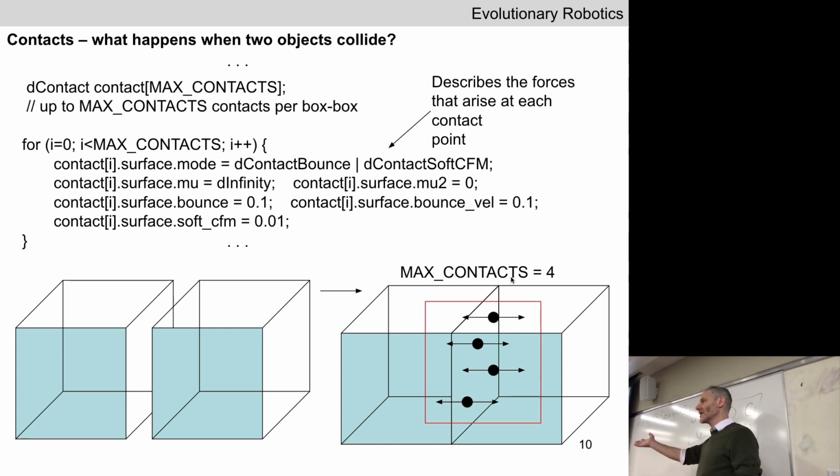In most physics engines, if you want to get down under the hood, you can set the number of contact joints that are spread by the physics engine into this estimated region of interpenetration, where these objects are either touching or already starting to collide. The more points you allow the physics engine to sprinkle, the more accurately it's going to resolve collisions between objects and figure out how they should rebound away from one another. But it's going to cost you. It's computationally intensive.